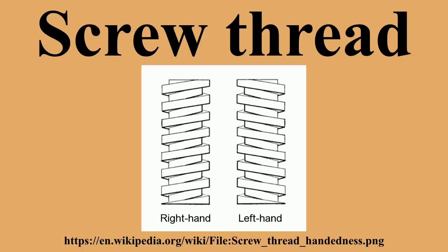The part of a fastener's thread crests will have burrs upon cutting, and will be too susceptible to additional future burring resulting from dents. The roots and crests of mating male and female threads need clearance to ensure that the sloped sides of the V meet properly despite error in pitch, diameter, and dirt- and nick-induced burrs. The point of the thread form adds little strength to the thread.